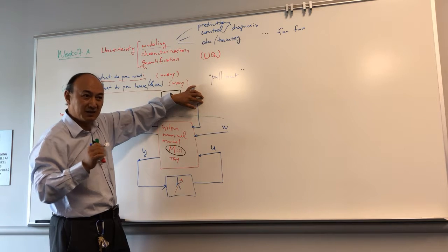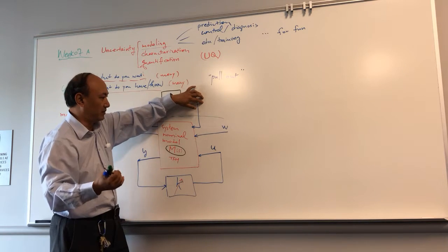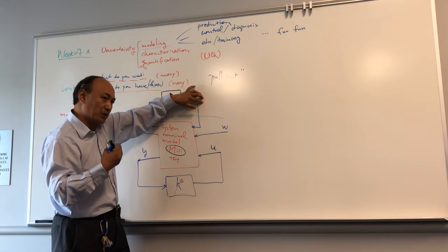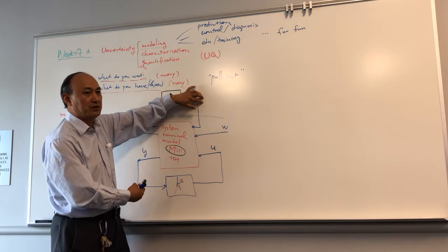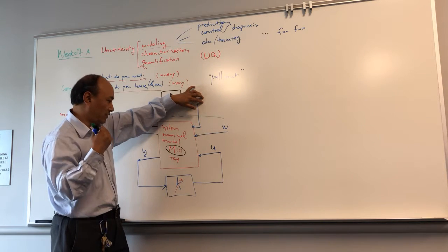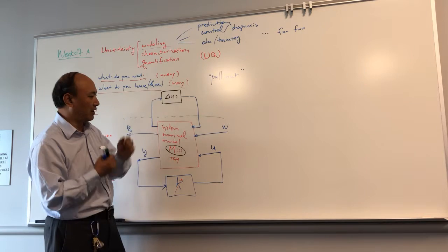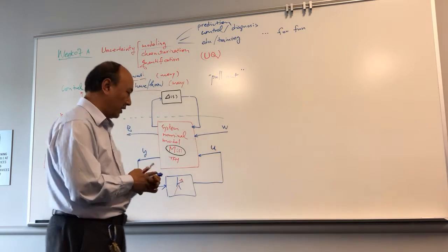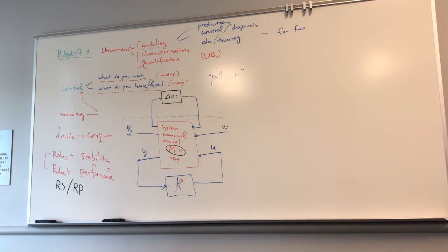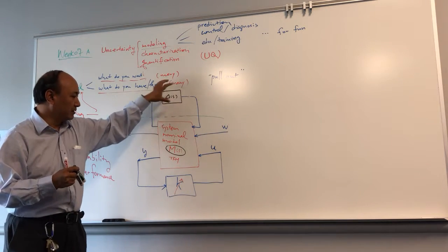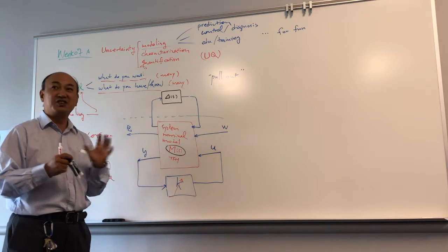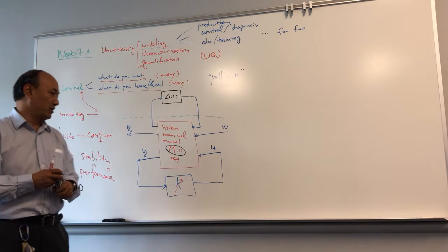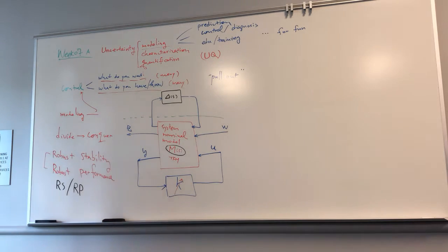But if you make this one work in the real system, you have to consider, do you have the robust stability? Do you have the robust performance property? So that kind of robustness issue, meaning even if I have perturbation uncertainties here, my performance is still satisfactory under that bound. So that's called robust performance or robust stability.